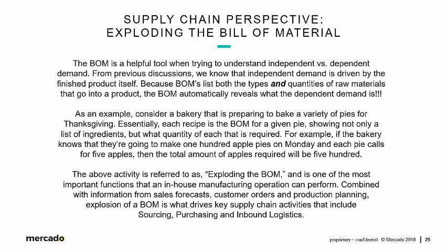Or, going back to our previous example, for the spring for the large pulley, we need 1. The cotter pins, we need 2. And the nuts for the threaded rods, we need 4. Either way, whether we're talking about a bakery or a real-world manufacturing environment that imports its raw materials, the above activity is referred to as exploding the BOM, and it is one of the most important functions for an in-house manufacturing operation.